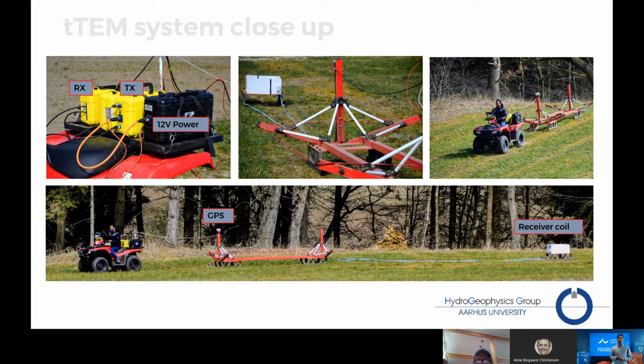The system uses a lot of power, in the sense that it's transmitting 30 ampere current, and we are repeating those measurements so fast that the system heats up. In order to keep the temperature below an operational limit, we have built a cooling system with the transmitter. The cooling system is always active, trying to keep the temperature at a constant level.